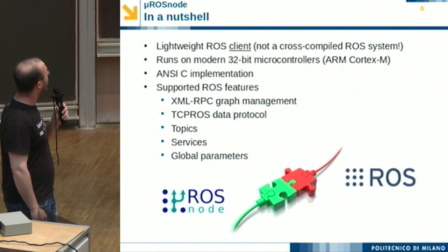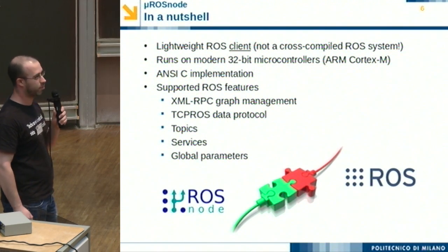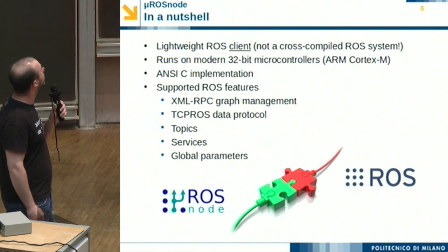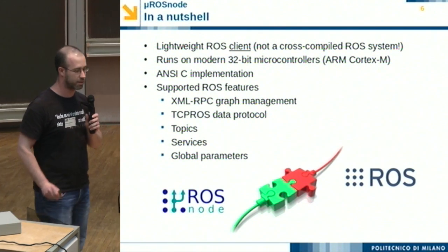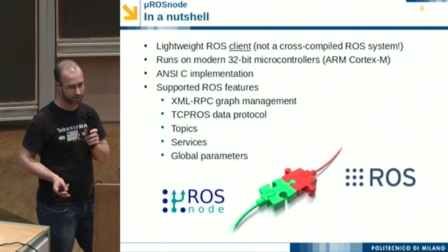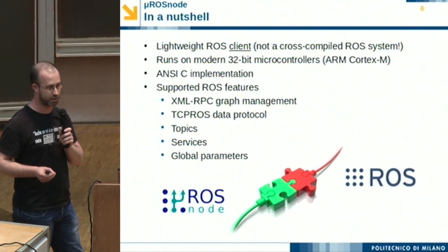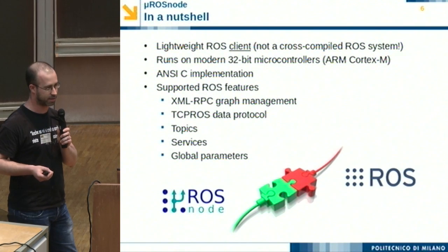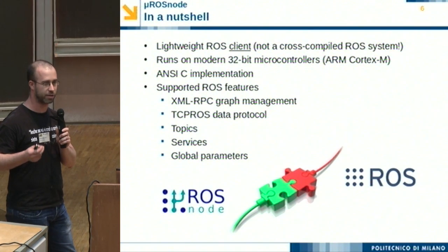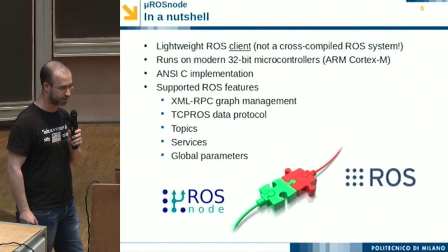This is why we started developing uROSnode, which is a lightweight ROS client. It is not a port of ROS to embedded systems. It is not a standard ROS client. It is just a library which can interface directly with ROS on microcontrollers.